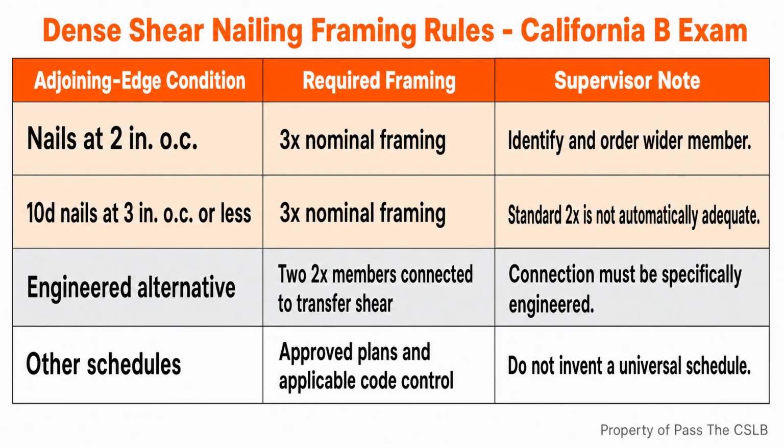The correction is not to pretend the row is complete. The missed location has to be addressed with a properly placed fastener or another approved correction that actually engages the framing. The superintendent should also look for the cause. The chalk line may be off, the framing may have moved, the panel joint may not be centered, or the nailer may be held at an angle. Finding the pattern matters because one visible shiner can signal repeated misses along the same line.